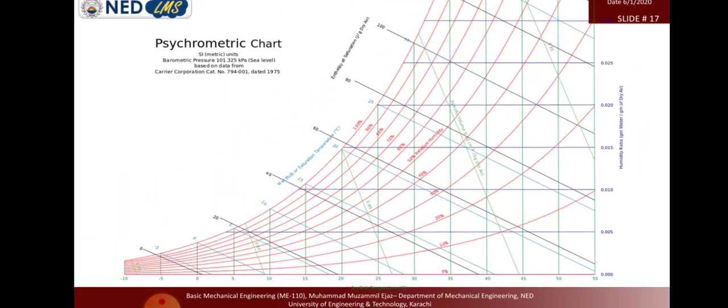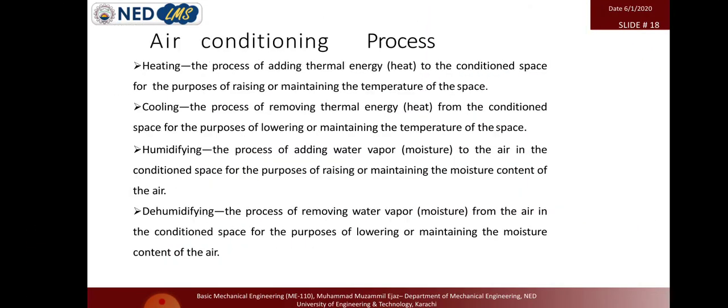So you can see that to do dehumidification, we need to do some extreme cooling, then reheat either by heaters, for a more specific and accurate air humidity and temperature, or secondly by mixing with the surrounding air. By mixing with the surrounding air, it gets reheated to a certain temperature to achieve 23 degrees centigrade.